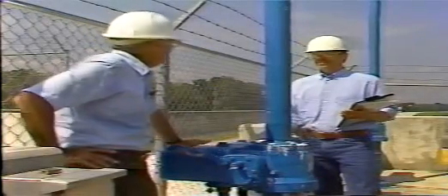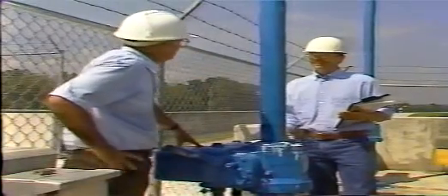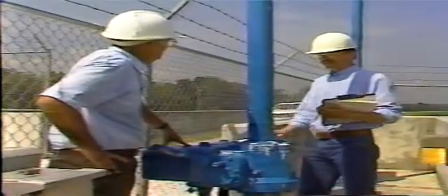Report your concerns to the facility engineer, dam safety inspection personnel, the owner, or other appropriate authorities. Also, make notes of the conditions you find. Include such details as location, size, amount, and other factors that will help describe a potential problem and its severity.